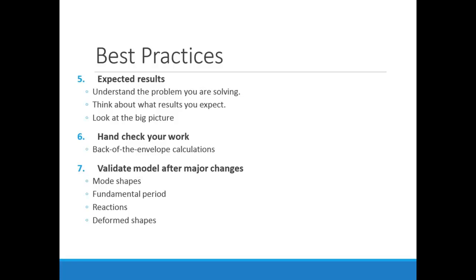The other thing that's quick and easy to verify is your reactions and then your deformed shapes. And the deformed shapes, easily just look at your user interface and see if that makes sense.